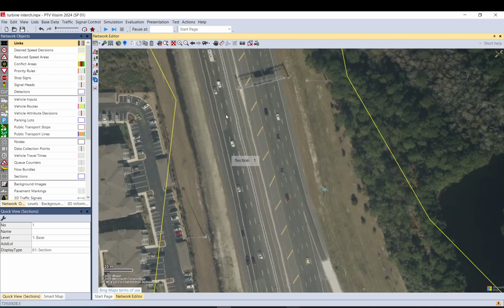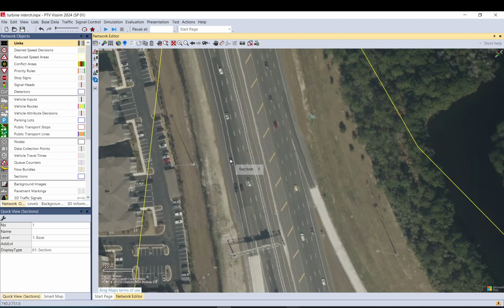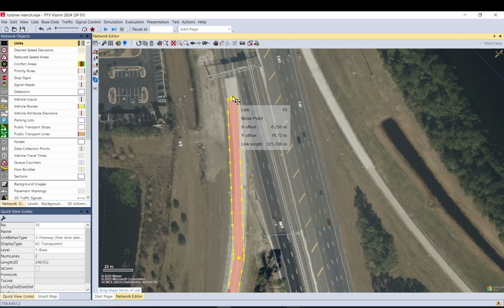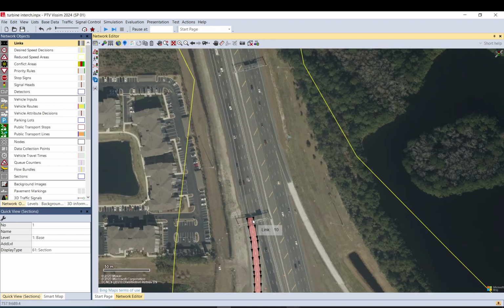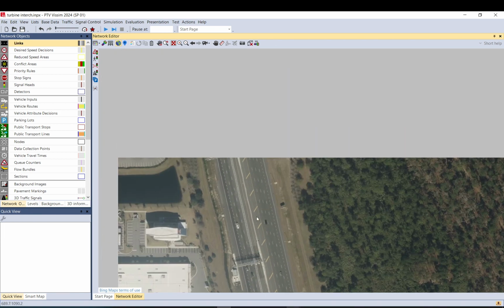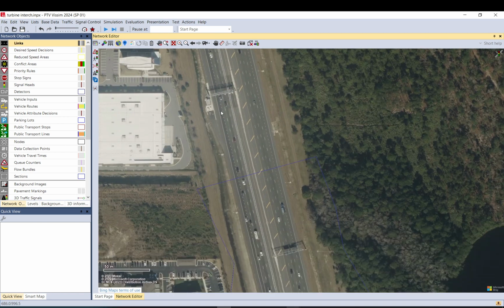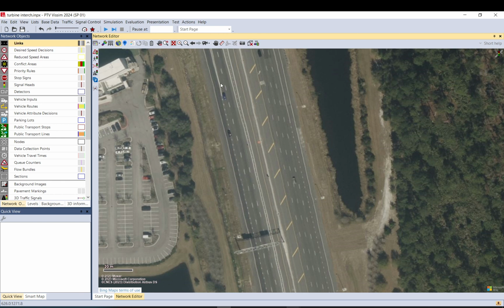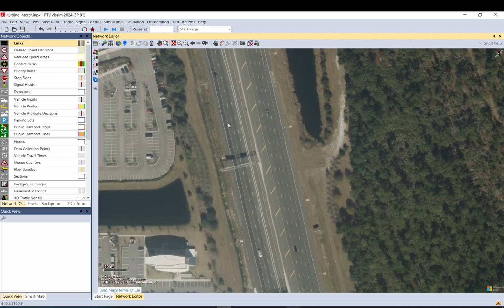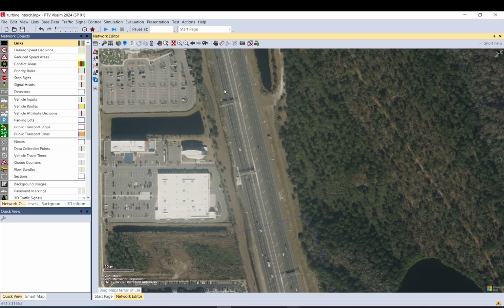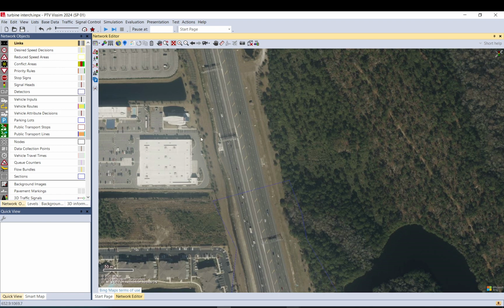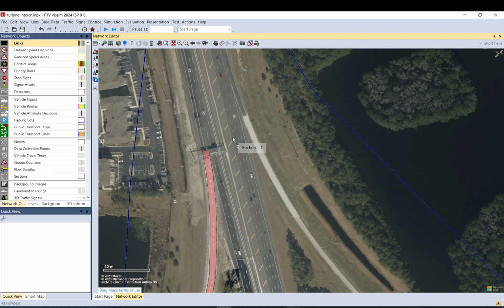So here I'm going to follow my previous way of modeling this as a two-lane exit because it is faster for me to do so. But I think that just from experience that works better, or in many cases it creates issues when it is not like that. So unfortunately it seems you have another weaving section. Weaving is when there is traffic going from this lane there and traffic going from that lane there, or more accurately between these exits. So from that lane going out to the off ramp from the main line and from the on ramp going onto the main line. So they basically weave when you have the crossing.